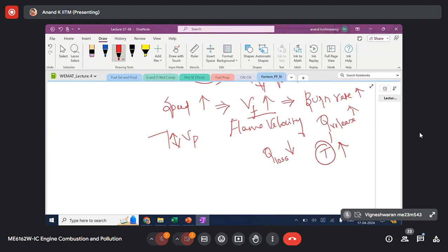One of the effects is that the temperature gradient is going to be high, because inside the cylinder, I already said, the temperatures are high. Let us say that you have some coolant temperature, right? The delta T is the difference in temperature between the cylinder gas and the coolant. That is what is available for wall heat loss. Across the cylinder wall, you have a heat loss from the in-cylinder charge to the coolant. That is the heat loss we are talking about here, and this is dependent on the temperature gradient. This is high, meaning it will have a tendency to drive more heat loss.